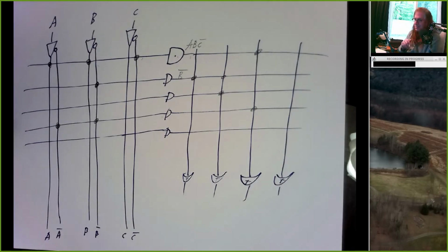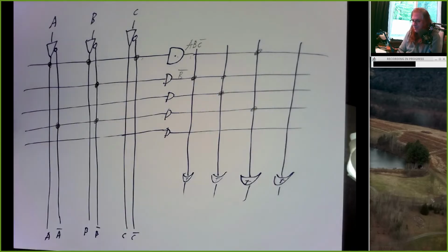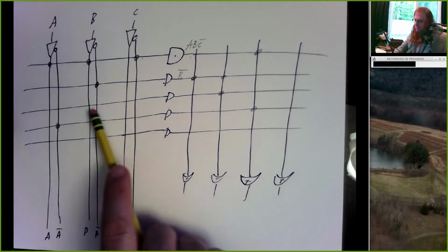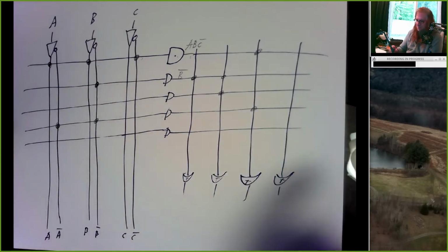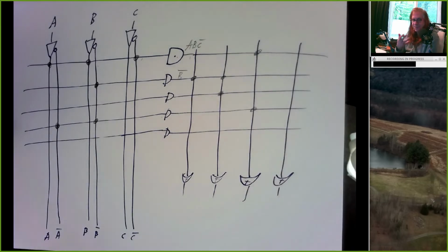But it turns out that if we think of our circuits in this way, we can get a device called a programmable logic device. And by telling it where we want our dots, we can program this device to act like a piece of circuitry. And so this type of device is called a programmable device, or programmable logic.